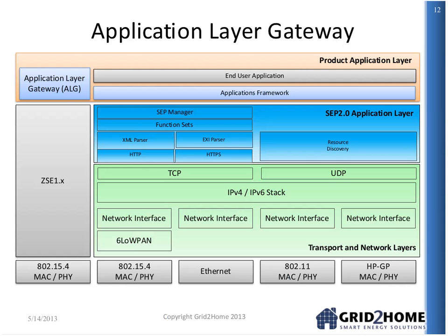At the very top layer, you'll see there's something called an application layer gateway functionality. That is the block where you convert data, not protocol; you actually exchange data at that top level, enabling you to go up the left-hand side and come down the right-hand side, or go up the right-hand side and come down the left-hand side. That little important block at the top on the left-hand side is what the ALG actually is. It's just a little square block, and it's really where data is swapped between the two protocols. But you've got to decode the full protocol, you've got to encode it, and it's going to be in the open at that point in time.